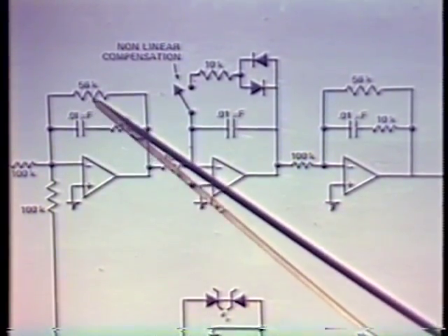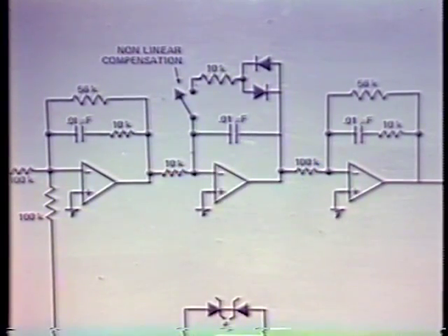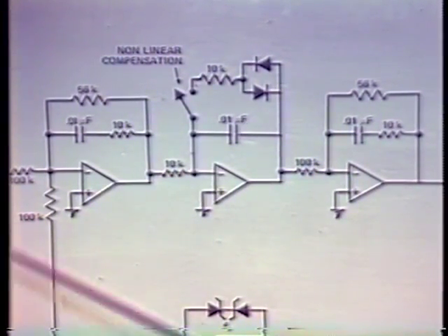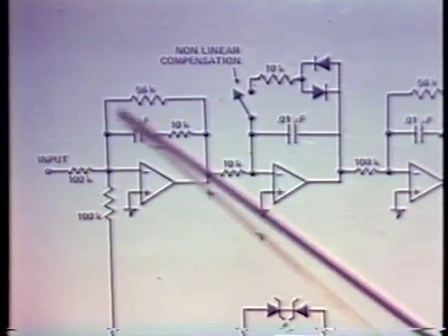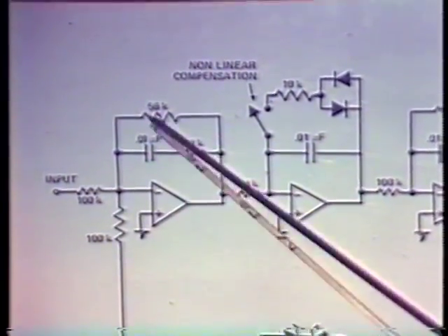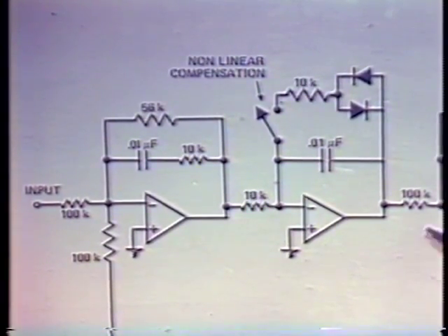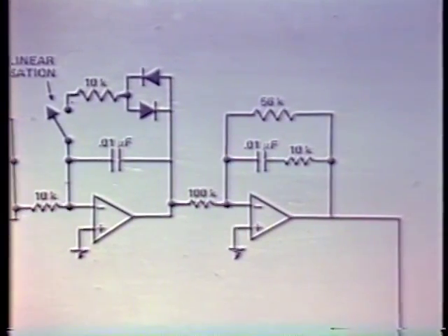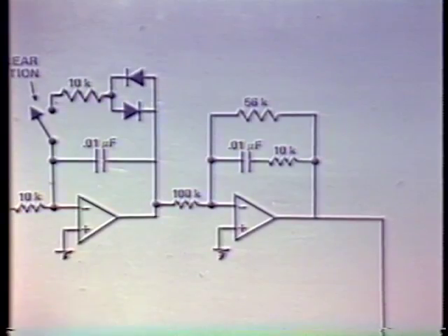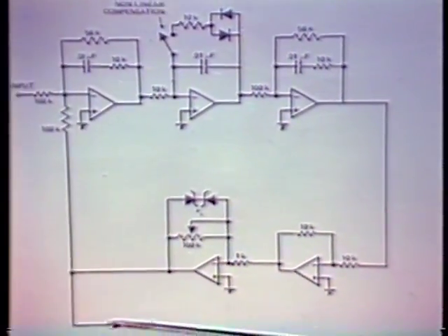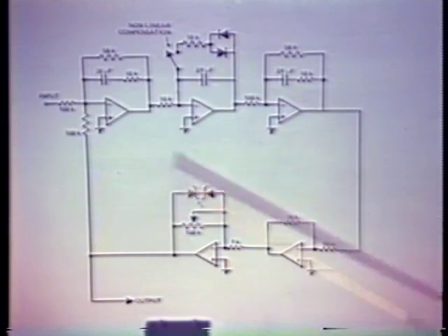And here we have the 2 operational amplifiers that give us the lag type transfer functions. At low frequencies, the gain of the amplifier is 0.56. At higher frequencies, it decreases by a factor of 6.7 if you keep track of everything. We have another really identical network here. We have the input to our system. This is really the feedback path. We consider this the output of the system. So this resistor provides the overall global feedback path.